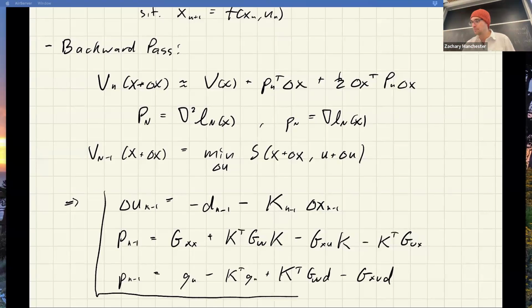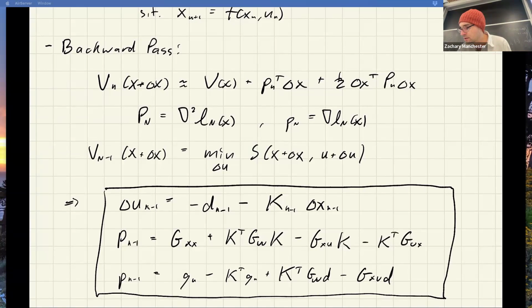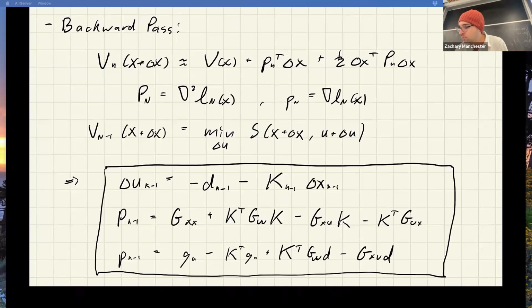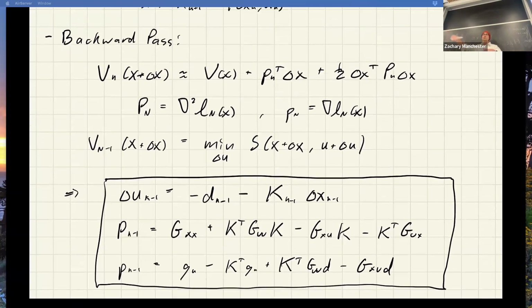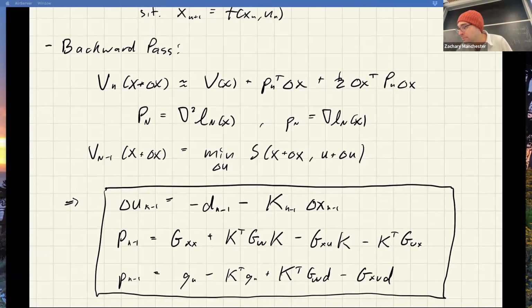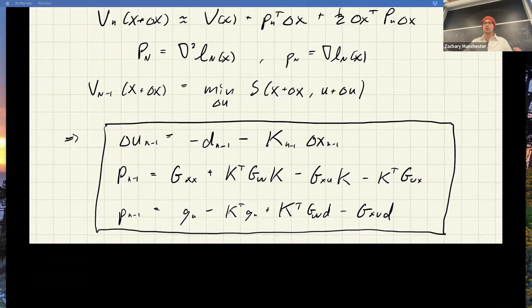And I'm going to write it out in kind of pseudocode form here with a line search. It's just the Armijo rule that we've been doing all along applied to this forward rollout. So the way we're going to do this, I'll write all the mess out. We're going to compute the change in the total cost as we go, and we're going to start the rollout. The new trajectory that we get after we apply this delta U, we're going to call the prime trajectory. We're going to start out at time step 1 with x1 prime equal to x1.